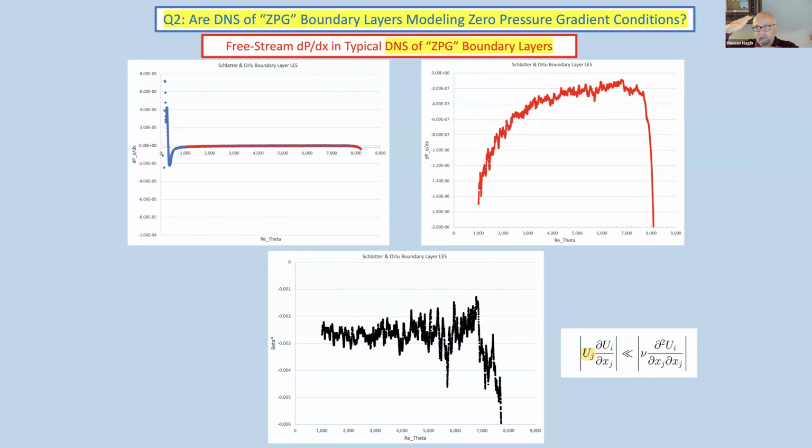The bottom, of course, is the wall, which is very easy. You need to aspirate the flow to allow the boundary layer to grow. In APG it is not as problematic. ZPG is supposed to be parallel flow near the wall and then growing. So near the wall, you neglect the advection terms.